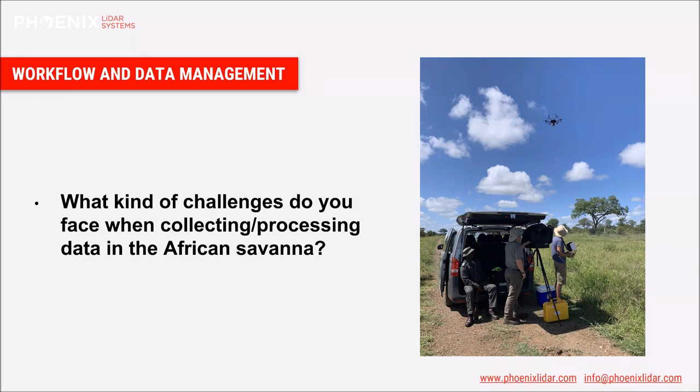But the biggest challenge, if you're doing subsequent flights, is taking care of batteries, especially on the M600 where we're really pushing that platform. The batteries come off so hot, you have to cool them off before you can charge them. Is that blue cooler used for your battery storage? That was lunch in that picture.